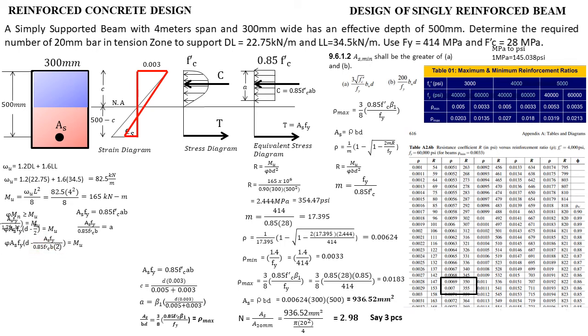Okay, let's simplify. Will give us this one. 1.7 is from the 0.85 times 2. Okay? So, substitute natin yung mga values na meron tayo. Ang unknown na lang is the As, the area of the steel. And φ is 0.9, since, as mentioned nga kanina, nagdi-design should be in tension control. Okay? And kinonsider natin kanina dito is tension control. So, now, isang unknown,